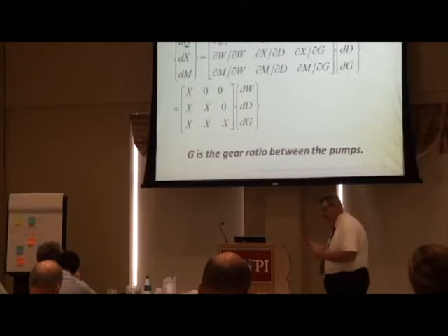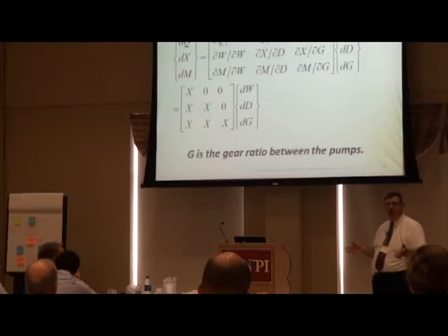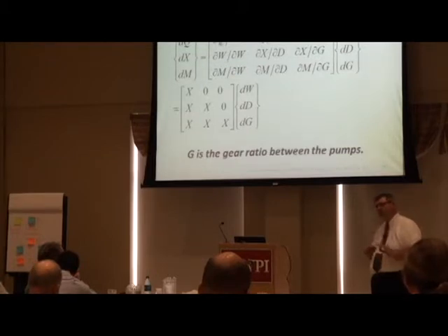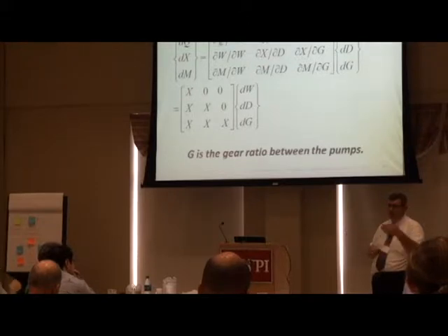And so you'll find the operators, as they become more experienced, they'll start out at a known rate and they'll say, well, the thing will cut at 100 inches a minute in 1/8 thick steel. And then they increase the speed 2% and increase the gas 2%. And then they increase the speed 2%, increase the gas 2%, until maybe they get to about 120 inches a minute.